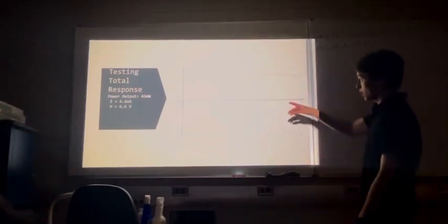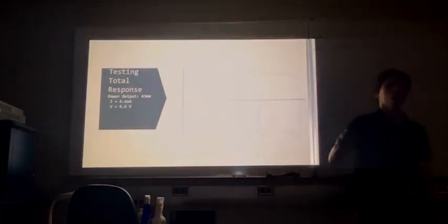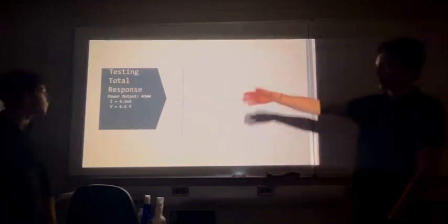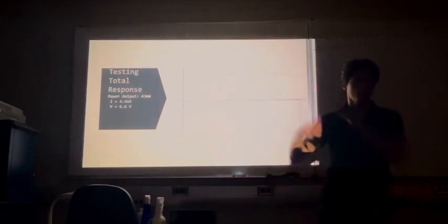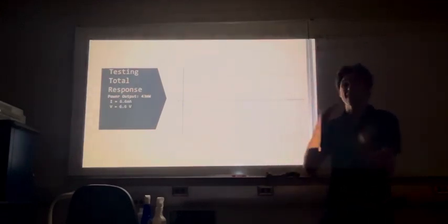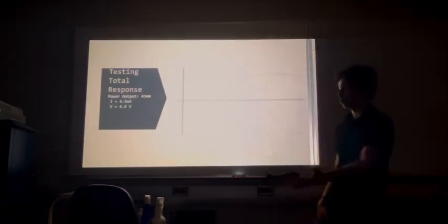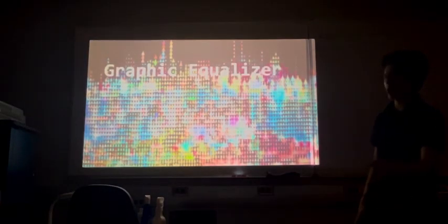So one thing on this one as well, the reason why the levels are not equalized is because every single filter uses different resistors, right? Which means every single filter is going to have a different power dissipation, as we showed in the previous slides. So as you see, these two filters are equalized because they're in similar frequency spans and they have similar bandwidths, while this filter still is a little bit lower, as when we were testing at the moment. That's a simple fix.